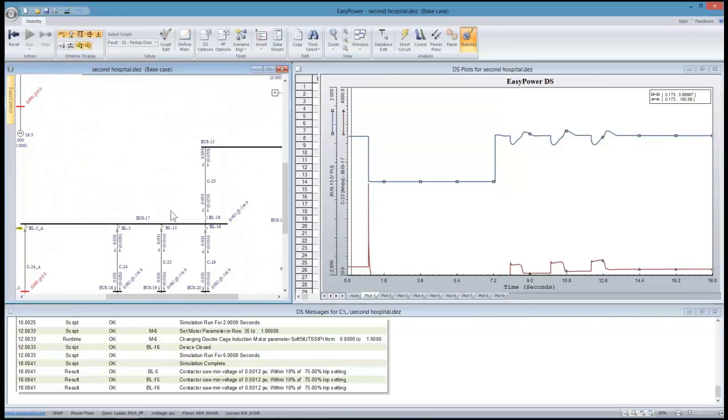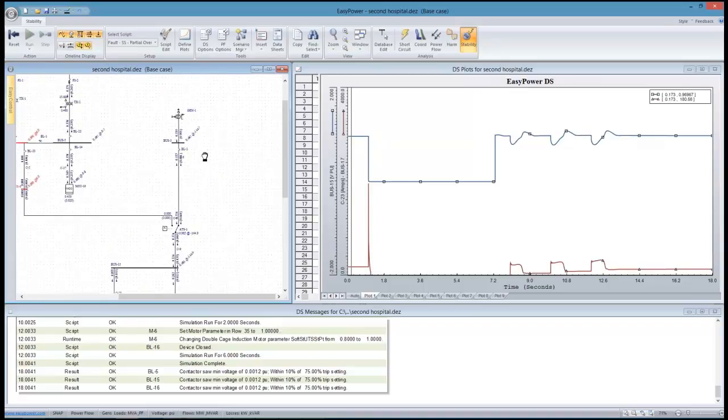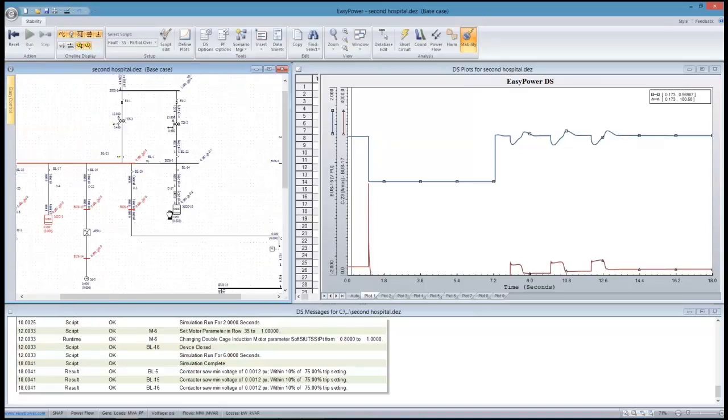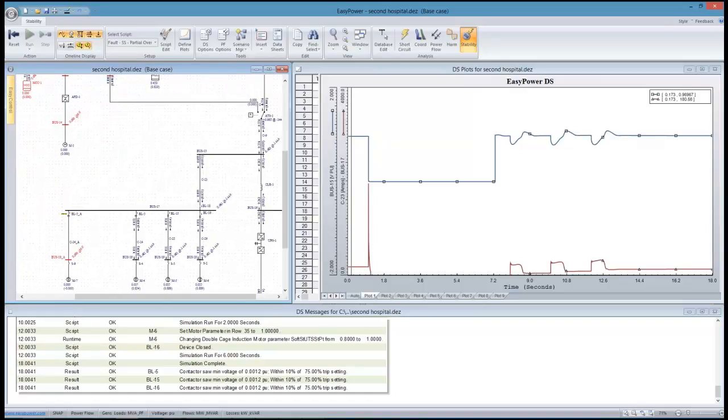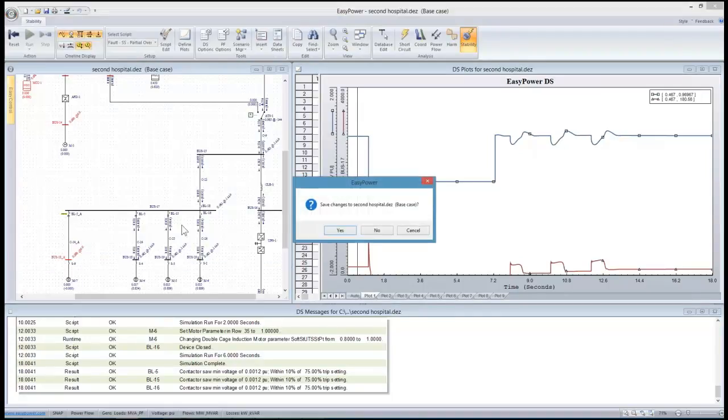Last week, you'll recall we talked about starting one major load and how it impacted the rest of the system. Here we're able to include the response to a generator coming online, and then because it's not as stiff as the utility or the main bus, inspect whether or not it's going to be able to survive multiple motors starting at the same time. Again, these are examples that are available for your examination and to see how the tools work.